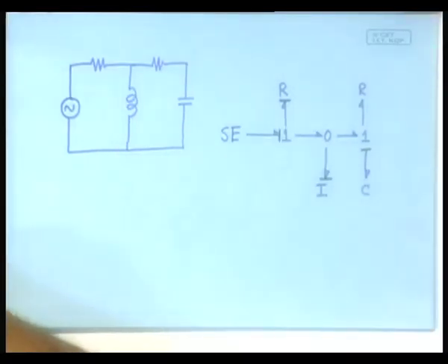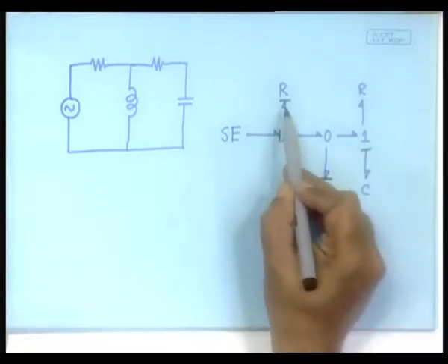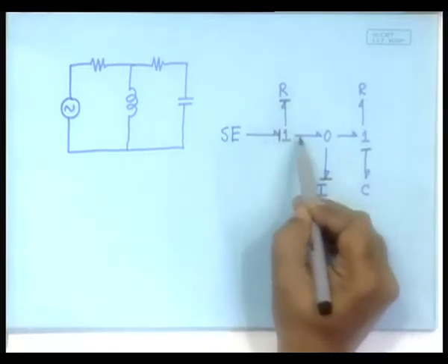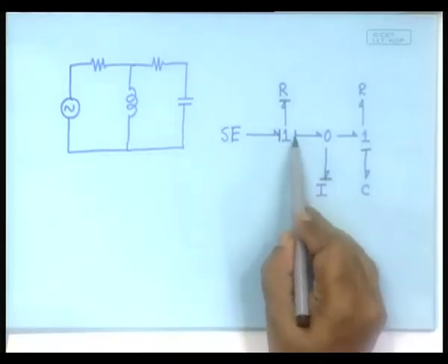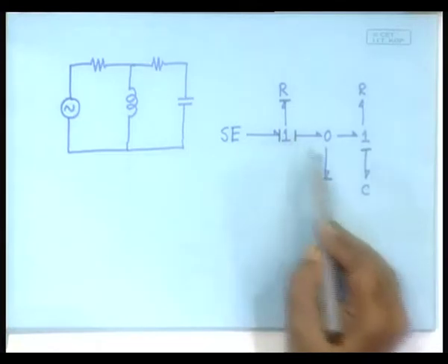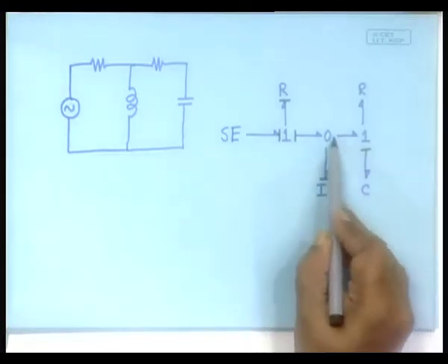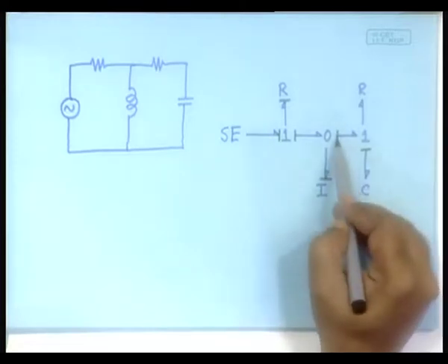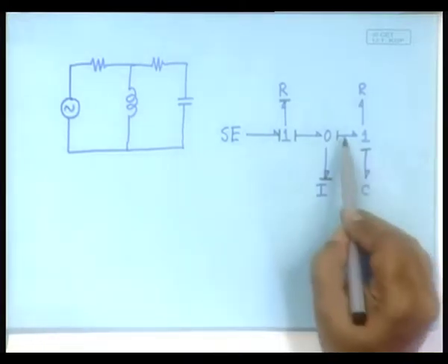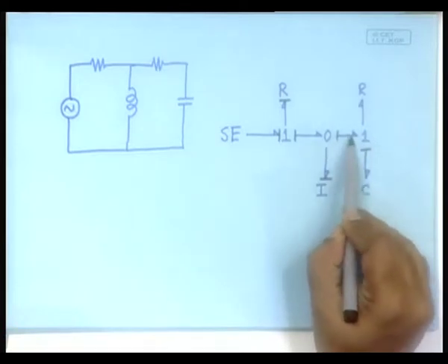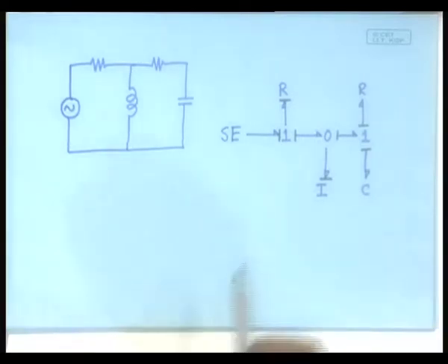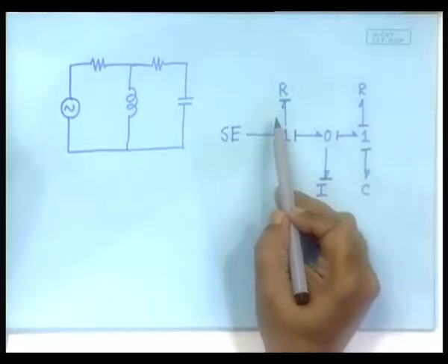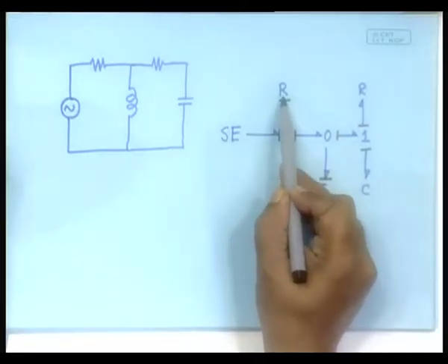Suppose, what does it mean? It will immediately make this one complete, because this has to take out the flow information. The moment this one has taken in the flow information and taken out the effort, this bond must bring in the effort. So, it has to be like this, right. So, this is the one junction in which the flow information has come, and it must be like this, done. But notice that you had to put this causality somewhat out of your hat.